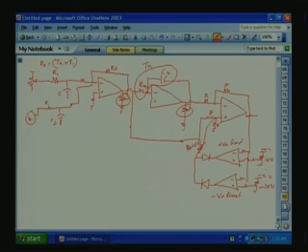Okay. Whenever this output goes above this value, that is, the output is more than this value, what will happen? The operational amplifier is in open loop gain, so the output goes negative, and this negative output will immediately come here and reduce the gain. This open loop gain is very high, so this error will slowly decrease, and the error between these two will become very minimal, such that this output will have the correct value to limit the output excursion to plus 10 only.